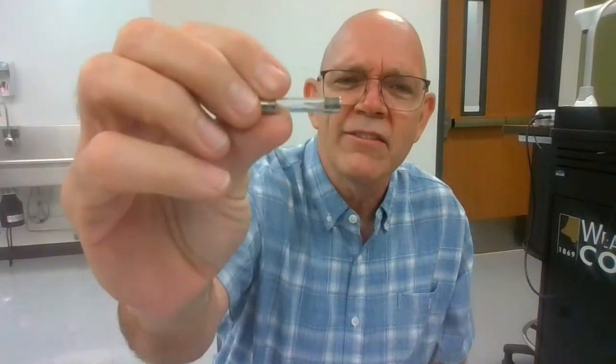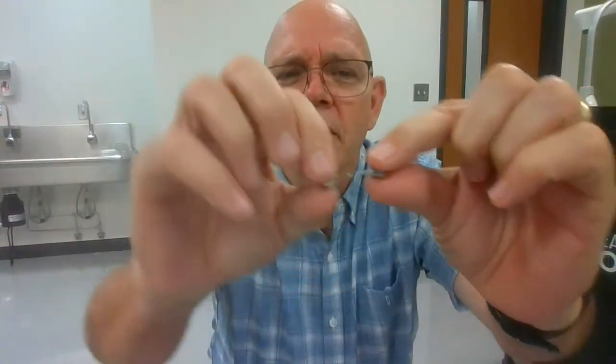Okay, we also have fuses. A lot of electrical equipment has this kind of fuse, this glass one. I don't know if you can see it in there, but there is a little piece of metal. Here's one where you can probably see it, since the glass is broken. Basically, you have a glass tube in the middle, and you see that piece of wire. Depending on what amp fuse it is, if it gets more amps than that, it will melt and open the circuit.